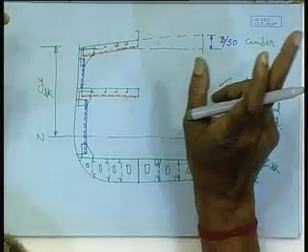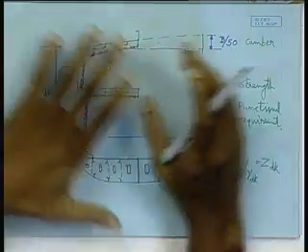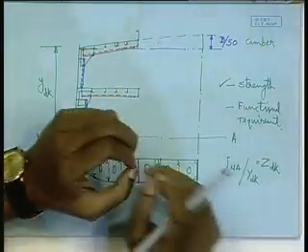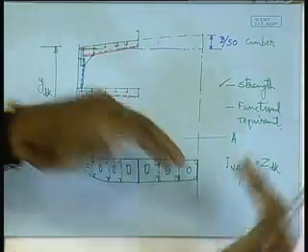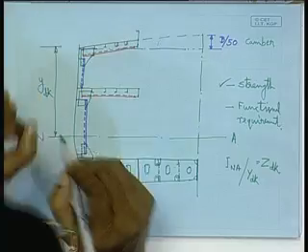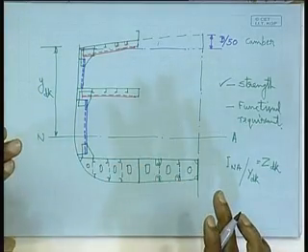You have the bending moment distribution. So, divide that by this, you will get the stress value. If that stress value turns out to be higher than the working stress, what has to be done? That may happen. All this you have done by taking the scantling from the classification rules, calculated and put. Based on that, you have chosen the dimension of the deck longitudinal, based on that you have chosen the thickness of the inner bottom plating, etc.